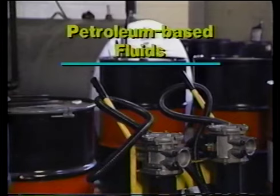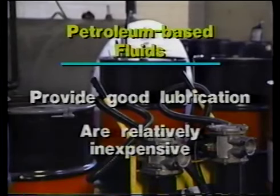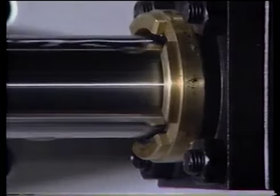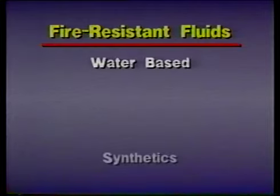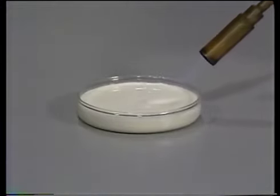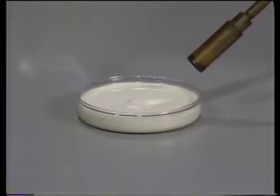Petroleum-based fluids have become the fluid of choice in most industrial hydraulic systems. They provide good lubrication and they are relatively inexpensive to use. However, they can be a fire hazard. If the oil gets out of the system, it can encounter temperatures hot enough to cause it to ignite. In situations where fire is a potential hazard, fire-resistant fluids are often used. These fluids are either water-based or synthetic. Keep in mind, however, that none of these fluids is completely fireproof. If you get a fire-resistant fluid hot enough, it will burn.